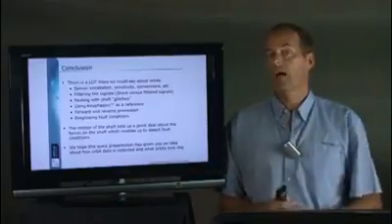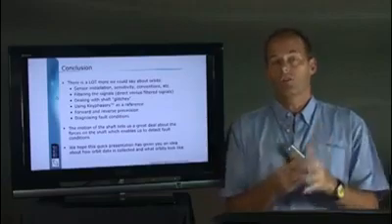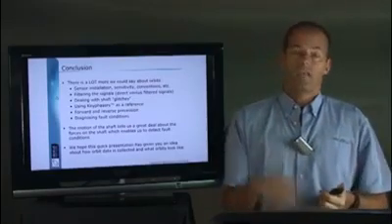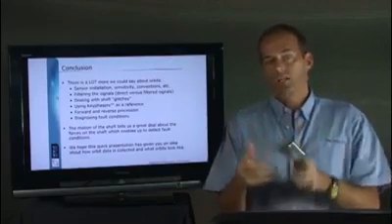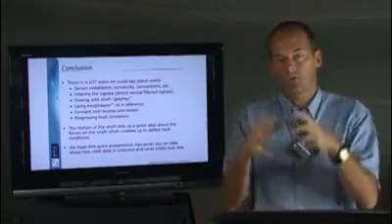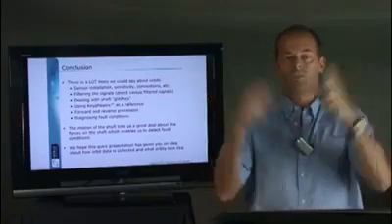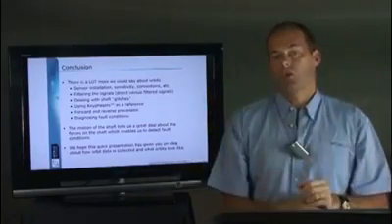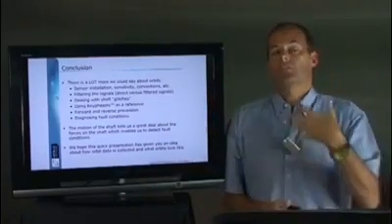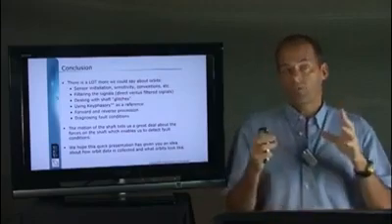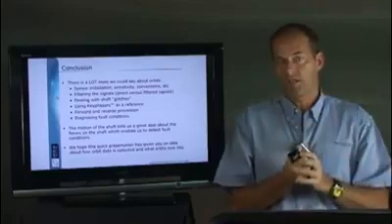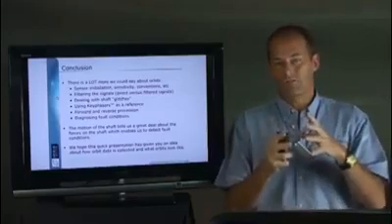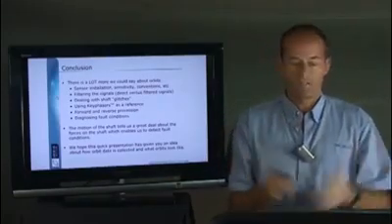Putting an accelerometer up on top of that bearing does not give us that same information. It's only one-dimensional for starters, plus the vibration inside can be heavily damped as it goes through that fluid film up into the metal of the bearing and up to the top of the accelerometer. We still sometimes use the accelerometer so we can see how the bearing is vibrating compared to how the shaft is vibrating, and with that we can tell how the shaft is vibrating relative to ground, but that's another story as well.